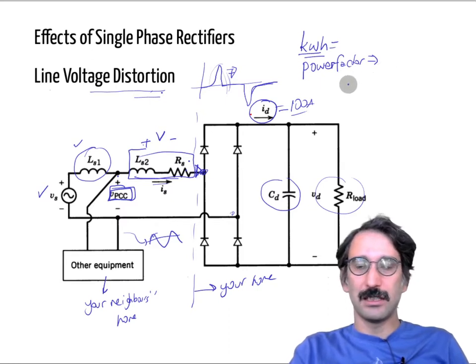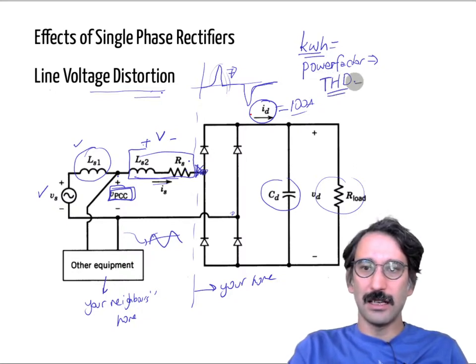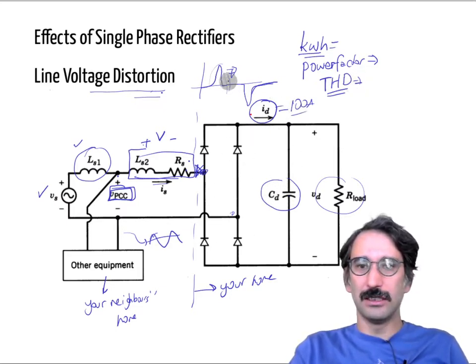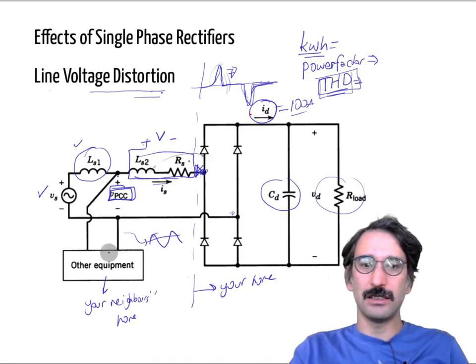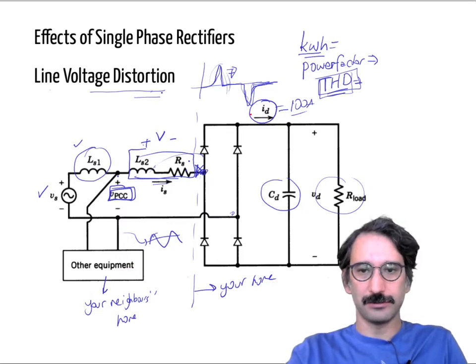And actually we discussed those things in the third year. And on top of that, they are also measuring the THD. So what is the current harmonic? If you connect that kind of harmonic inducing equipment, it is your responsibility to put on proper filtering, so the harmonics that you generated are not injected into the grid and are not affecting other people's equipment, right?